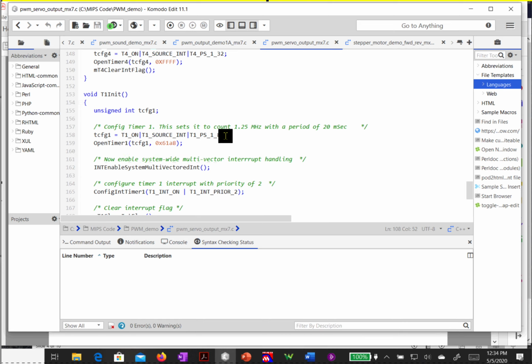So what we have to do is we configure it with a prescale such that we can get a reasonably large number in the timer register, and in this case with a prescale of 8, we can have it count up to 61A8 in hexadecimal. We know our max count is FFFF, and so if I prescale it by 4, I could actually get that a little bit higher, but was a little conservative in terms of letting the maximum count, approaching the maximum count.